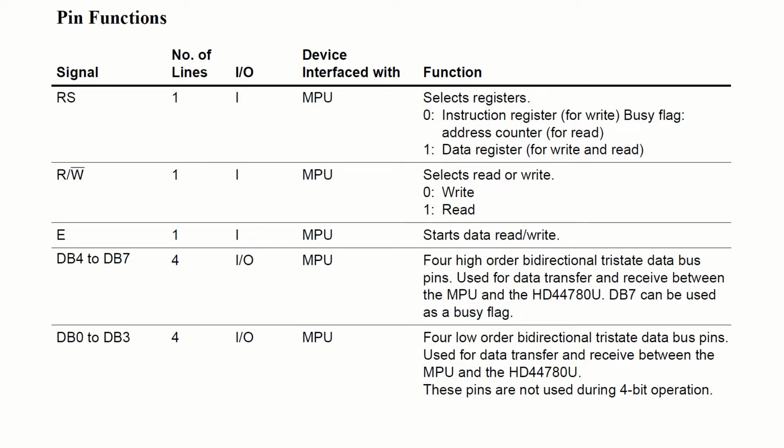It needs to be set to 0 when we want to write data to the LCD, and 1 to read from it. The third signal is called RS, and it tells the LCD if the bits on the bus are a command to be executed or data to be sent. The communication with the LCD is performed by sending commands which may be followed by data.